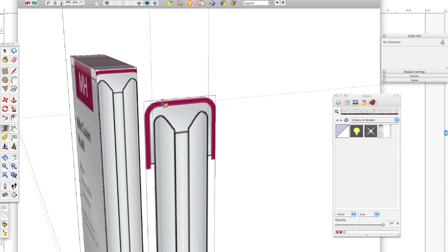And I think what I'll do is we're going to offset this 1.5 inches from the top using the guide. Remember, that's a tape measure. Because I'm considering this 1.5 inches to be the actual radius. Draw another guide down 7 inches, because that's the location from here to the top.